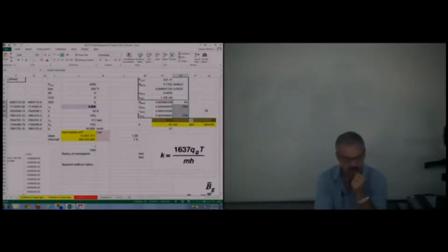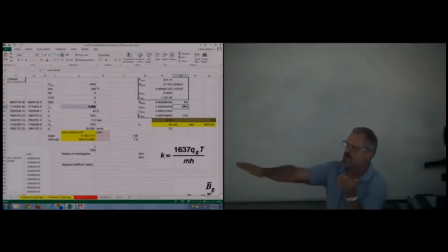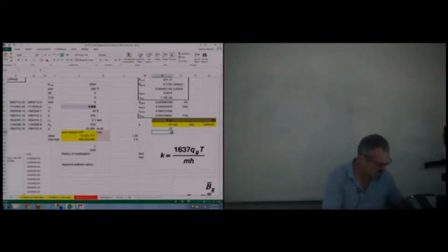Which errors? The error in the formation volume factor, and a big error there is in viscosity. These tend to get into total system compressibility. They have a different viscosity function throughout this book, and viscosity is used to calculate pseudopressure. So my pseudopressure and their pseudopressure that they get PAs from are going to be slightly different. They tend to wash out a little bit, but based on the gas gravity and what I think is a better, let's say that my number is the right number.